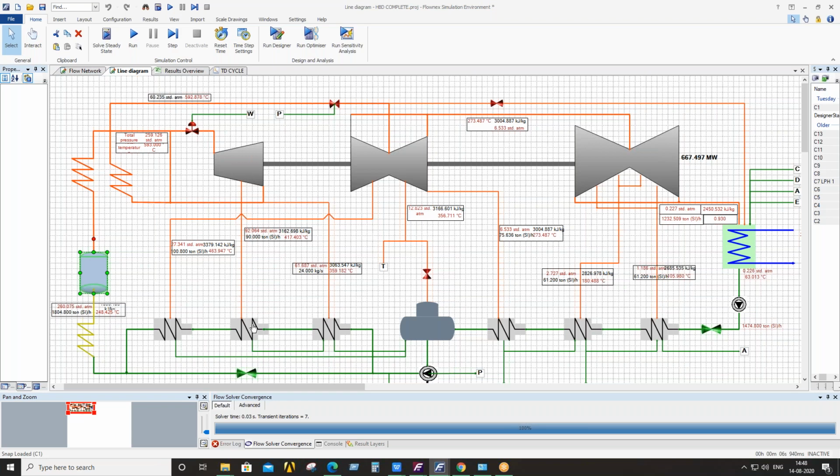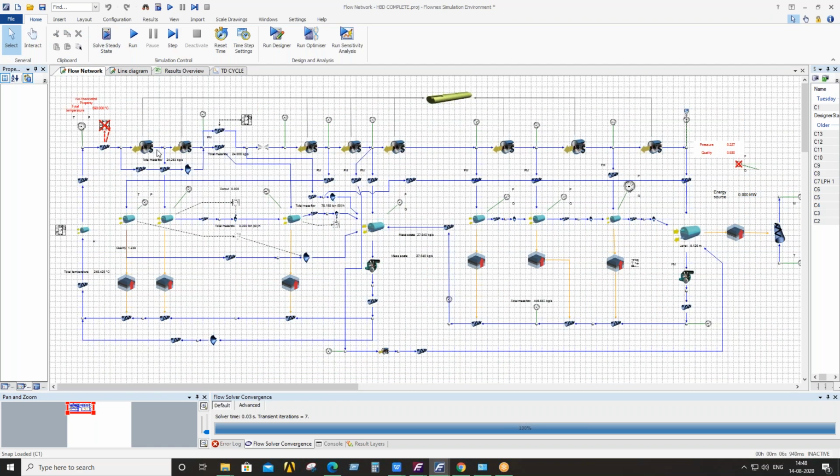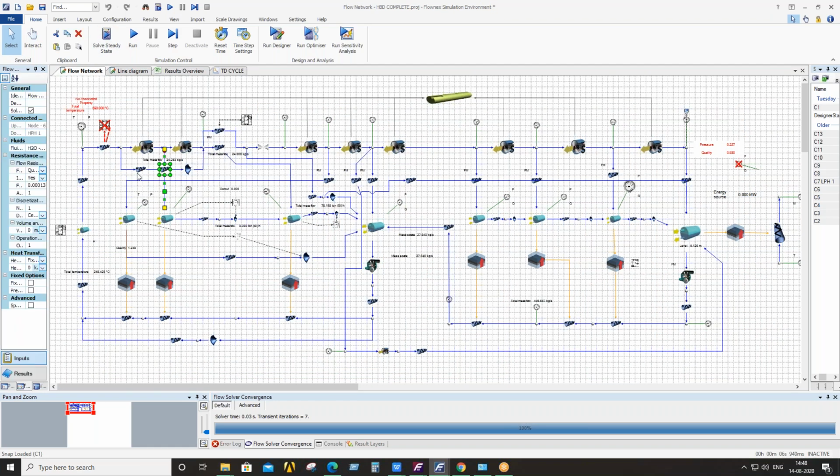this is the extraction lines which I have previously mentioned, and again it goes to your cold reheat lines. And you can see from this diagram, it is the extraction lines, it is the bypass lines, it is the reheater, and it goes to another extraction lines, and it goes to the IP turbines. And from the IP turbine also there are several extractions, one for the boiler, one for the desuperheater, and this cycle continues, just like what I have previously mentioned, the subcritical power plant.